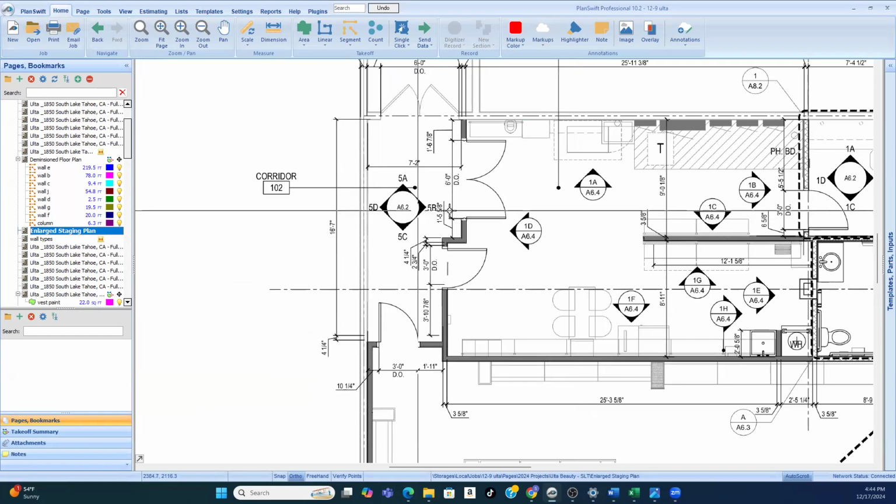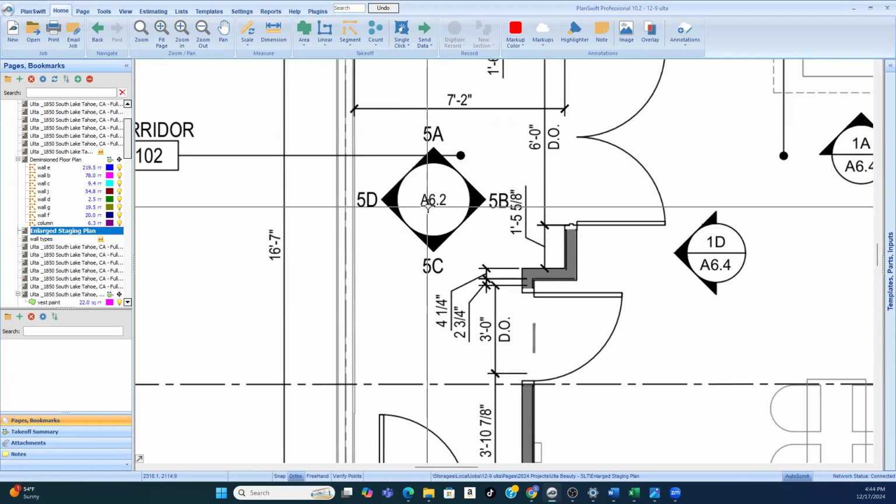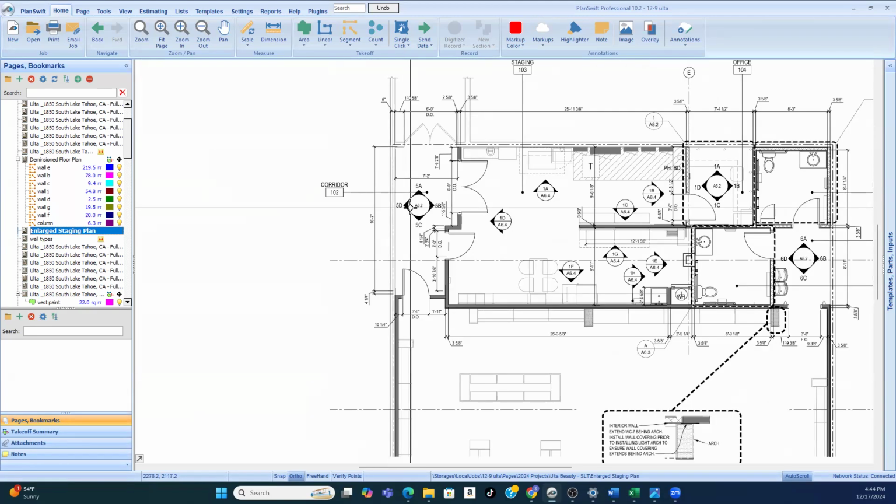But then we also have, in this case, exterior elevation views. And hopefully the exterior elevation view will show us from the bottom of the building all the way to the roof. And so maybe that'll assist us in determining the length of the studs, because once we look at the schedule for the studs, we can determine whether they are just to the top of the ceiling or all the way to the roof rafters and braced to the roof rafters.